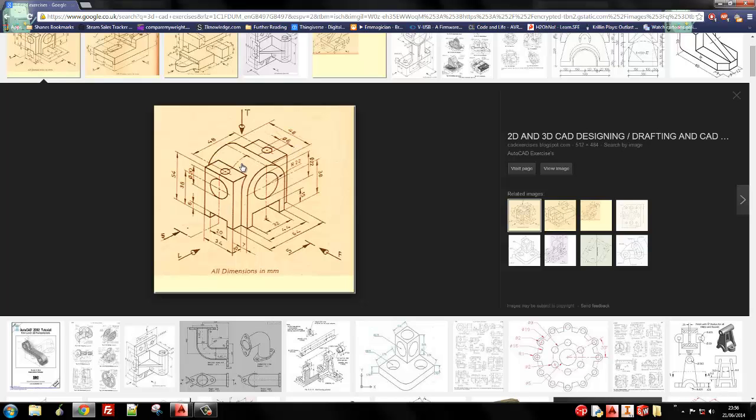Now the only problem I'm going to foresee here is that when we push this into this object, okay, this object obviously is going to be solid through the middle of here, so where we've put our nice clean cut through hole here, there's going to be this hulking object passing through it. So it might be that we have to come back and re-drill this hole and also re-drill this slot.